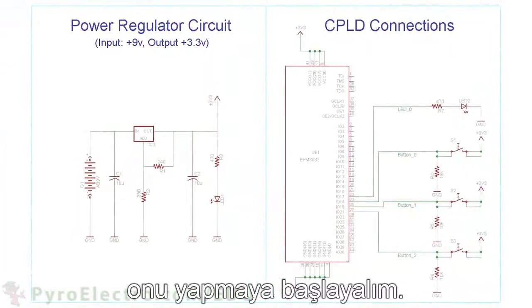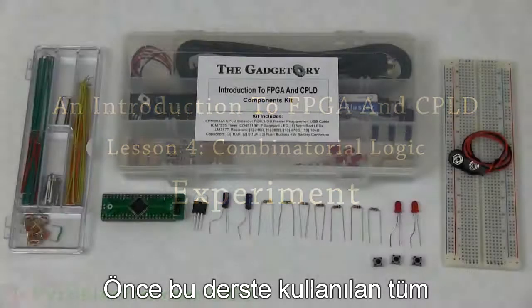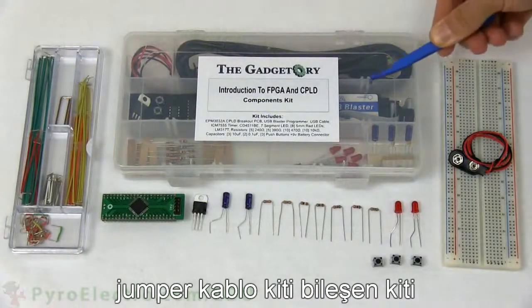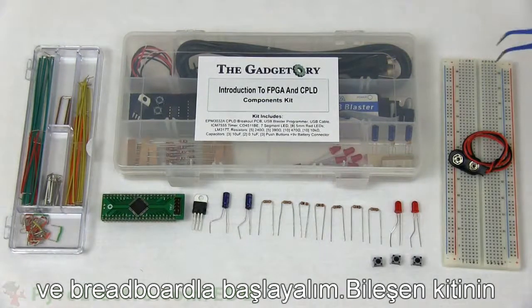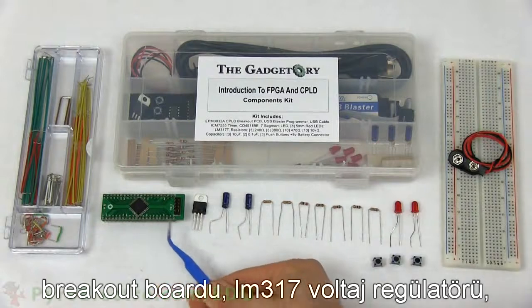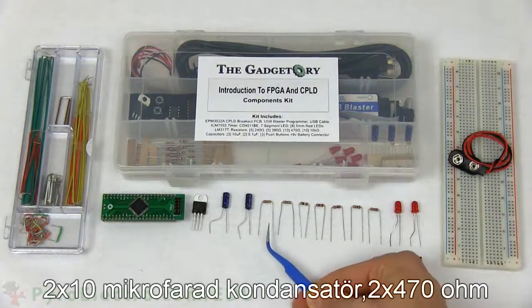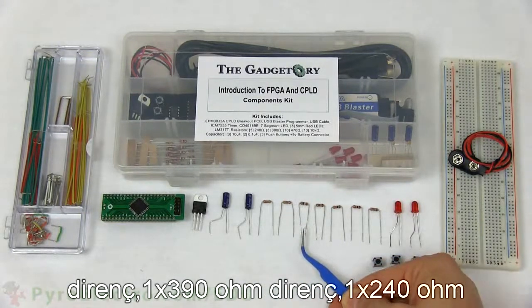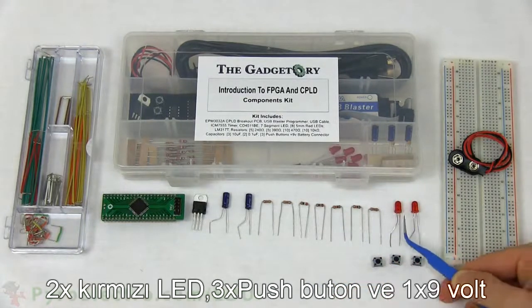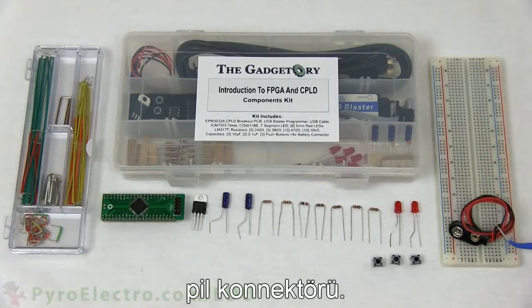Now let's go build it up. First, let's look at all the parts that are used in this lesson. We start with the jumper wire kit, the components kit, and a breadboard. The specific parts from the components kit are the CPLD breakout board, LM317 voltage regulator, two 10 microfarad capacitors, two 470 ohm resistors, a 390 ohm resistor, a 240 ohm resistor, three 10 kilo ohm resistors, two red LEDs, three push buttons, and a 9-volt battery connector.